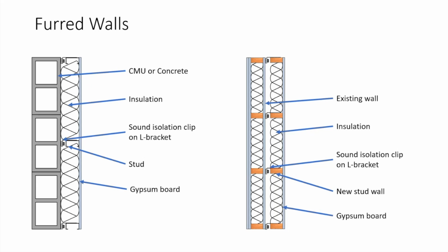So you'll build a typical stud wall, and you could just separate the stud wall from your CMU block wall or your wood stud wall, and just use that separation, that gap, as your isolation. That works totally fine. But that means your stud wall has to have that height, have the span on its own, have the structural capacity, which may mean wider studs, more studs, thicker studs, heavier gauge studs. So oftentimes those furring walls will get braced back to the primary structural wall.